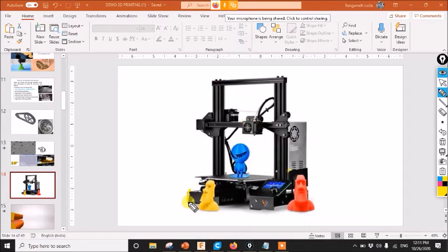This particular small box down here, we call that the CPU. Here you will be inserting your memory card, whichever you have converted into G-code. You will bring it and insert it here, and from here the machine will read and print the object. In order to monitor and understand what happens exactly, you have a screen down here. You can observe everything on the screen.